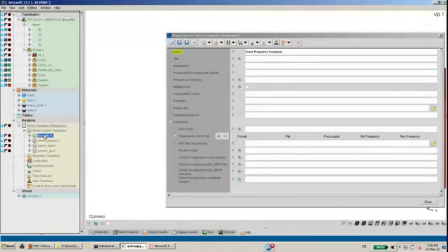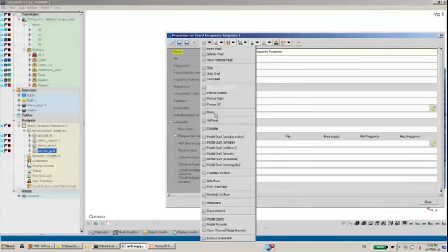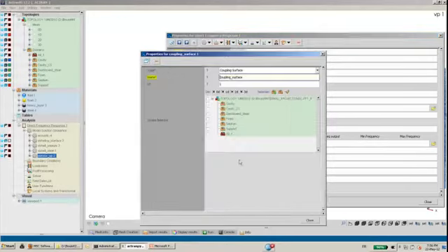So now on the left-hand side, I have my acoustic cavity, I have my septum, I have the steel, I have the porous material. So I have all the physical materials needed, but I still need to couple the structure and the cavity. And that's done through first a definition of coupling surface. So first an acoustic coupling surface that will be applied here to the 2D elements.